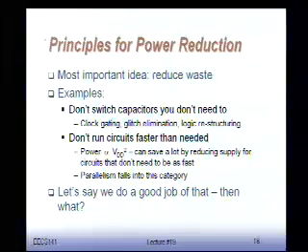Well, option number one, obviously, and that's something you definitely should consider, is: can I use this to reduce the supply voltage, for instance? If I reduce the supply voltage, my circuit is going to be slower, but I get my VDD squared savings. So reducing the supply is always a good idea. Running at the minimum supply is a good trick.